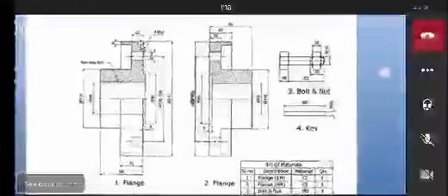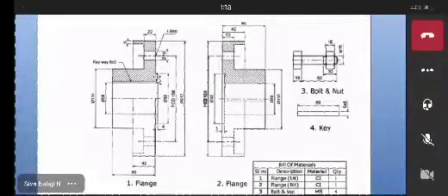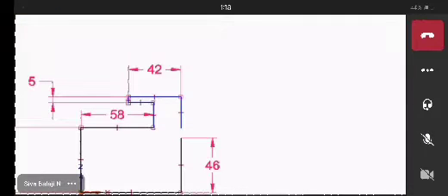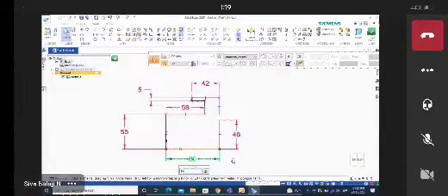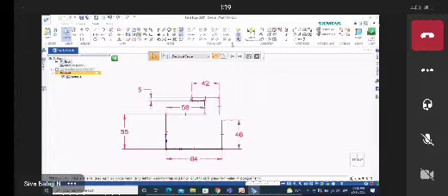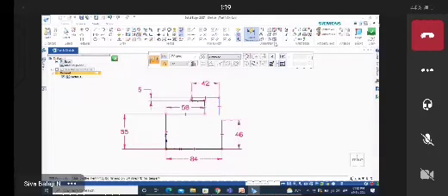Here in the 2D diagram, you can check it here. From this, the total outside is 4 mm. Outside 4 mm is there. For the dimension of this line, instead of 80 mm you can give 84, because you can check it here. This 4 mm is outside. He has given 4 mm here, so that's why you can change this dimension from 80 mm to 84. Okay, you can change it here to 84. Okay, now you can give a dimension for this line.